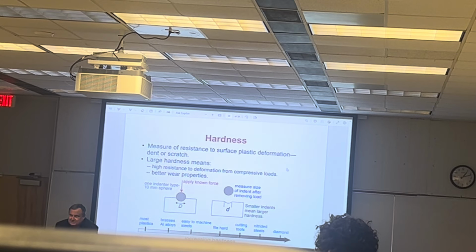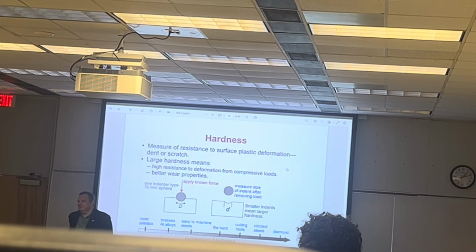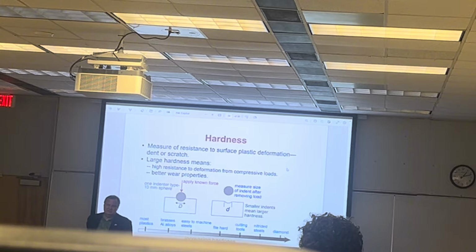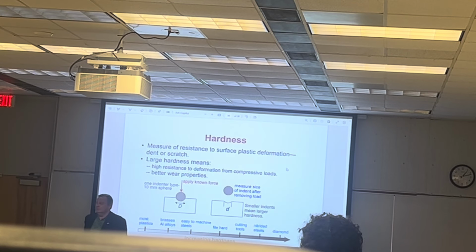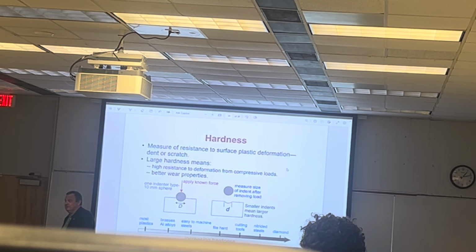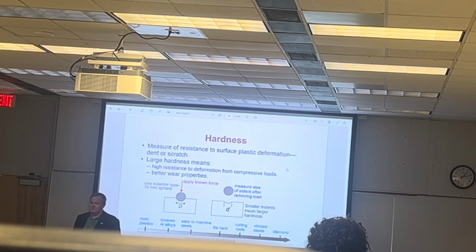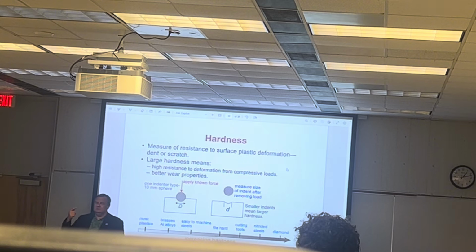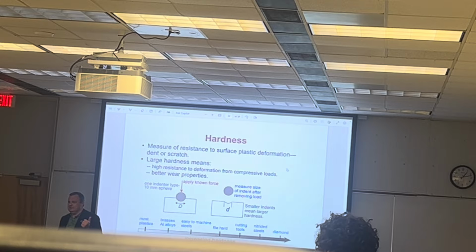And what would be the units of that? Load is measured in force per squared length, which is area, meter squared. So newtons divided by meter squared is Pascal. It's the same unit as the yield strength and the same unit as the elastic modulus, even though the elastic modulus is a slope, because the strain has no units.